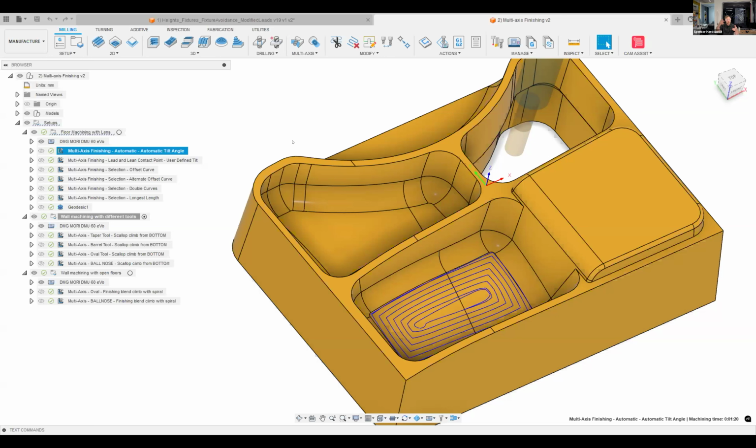For those of you that don't know, a little bit of tooling 101: circle segment tools are a little bit different to ball nose tools. Circle segment tools have a ginormous arc on them, whether that's on the side of the tool or the bottom of the tool. Essentially that allows us to take quite large step downs and step overs, which means we can drop the traditional cycle time that we would normally see with a regular bull nose, but maintain the same surface finish we would get with a traditional bull nose tool. So this is the first toolpath in Fusion that now supports circle segment tools.